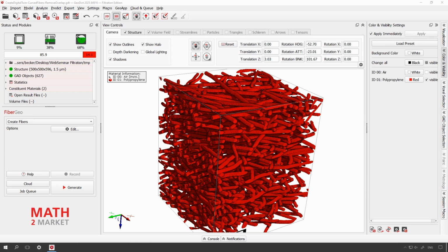You need sufficient accuracy on the simulations, but as you see here, in the example we had a voxel length for the structure of 1.5 micrometers. So this is one grid cell, and we have just considered particles lower than 1 micrometer. You get good numbers also for the very small particles, even if they are much smaller than 1 grid cell. But you need to have the flow around the fibers resolved.